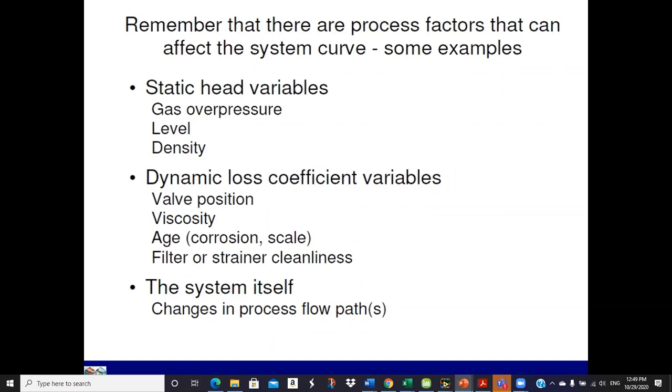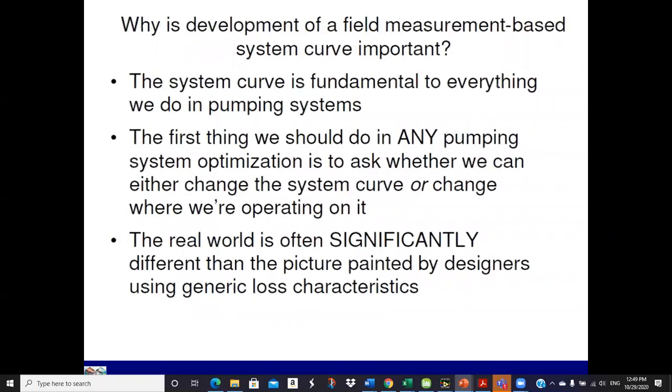And the system itself, sometimes we have actually changed the piping diagram, and that will obviously change a system curve. So all those things can happen. But why is this system curve so important? Well, it's fundamental to everything that we do. That's why in these slides we spend so much time on it, because everybody and their cousin that works with pumps knows about pump curves. But like 10% of those people understand system curves, okay? We want to make sure that you get both sides, because the pump is only half of the story. The system is the rest of it. So the system curve is fundamental.